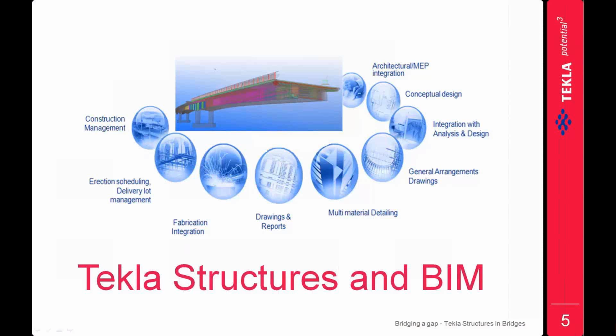The same can be transferred to an analysis application to do the analysis and design. Afterwards, we can bring it back and update the information in Tekla Structures, and then generate the general arrangement drawings. It supports multi-material, that means steel and concrete, and user-defined materials and user-defined sections.